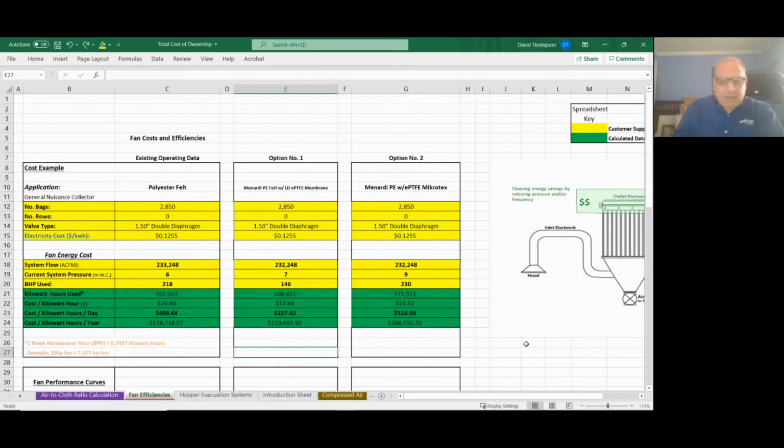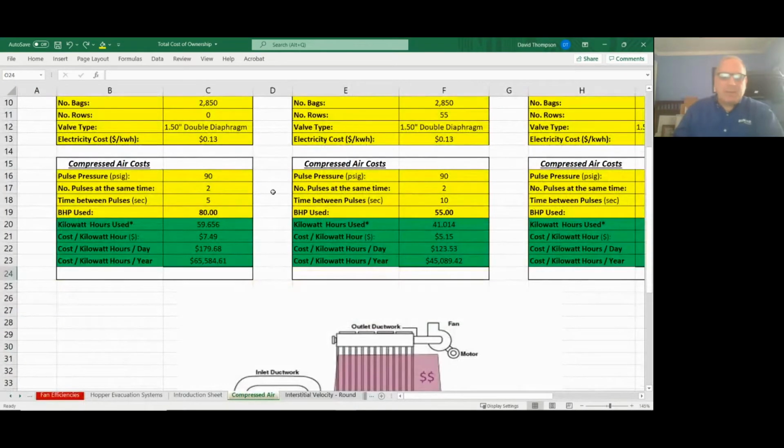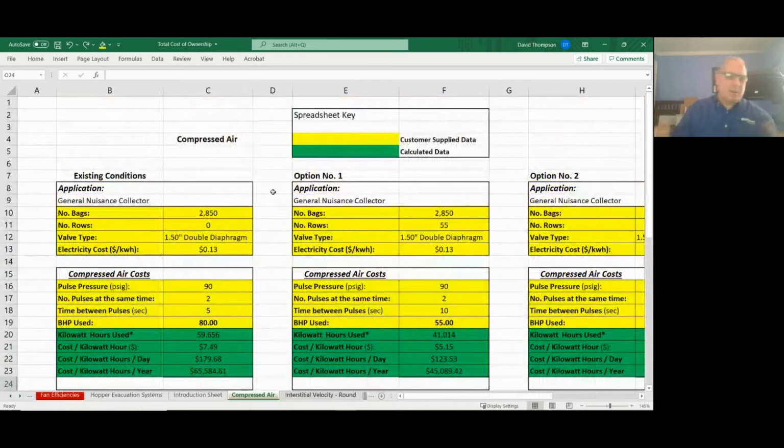What you have to look at and keep in mind with standard bags is that standard bags typically wear out from the inside, because in a pulse jet system, you are putting this bag on a cage. We recommend and specify a certain pinch or a gap around the annulus of the cage, between the cage and the bag, so that we don't prematurely wear the bag out.